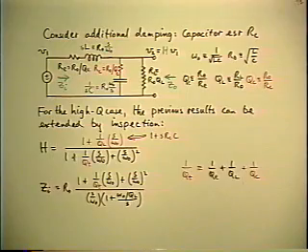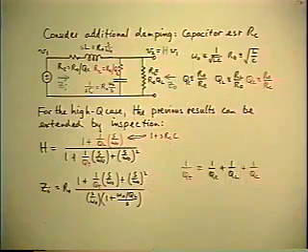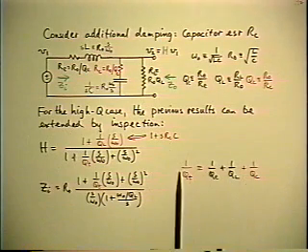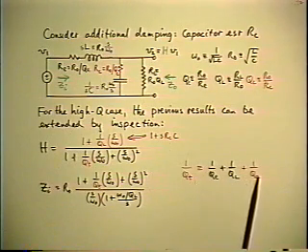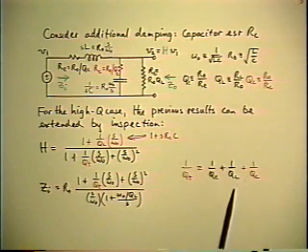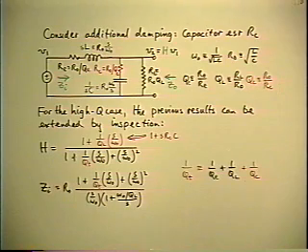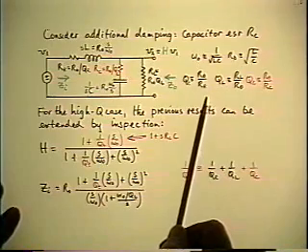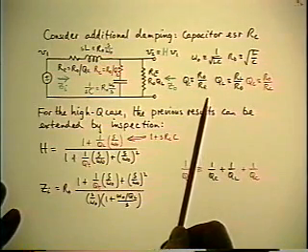And in line with our entire philosophy about doing analysis, make every assumption and approximation you can to begin with, plunge ahead and get an answer any way you can, and then go back and see if it's okay. So that's simply the same thing that we're doing right here. Let's make a guess that the total Q factor is a triple parallel combination. So that takes care of everything now except the possibility of new corner frequencies. But I've already mentioned how we check the effect of the analysis in the previous cases.